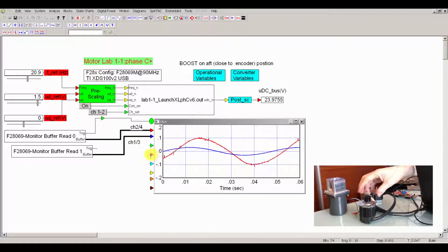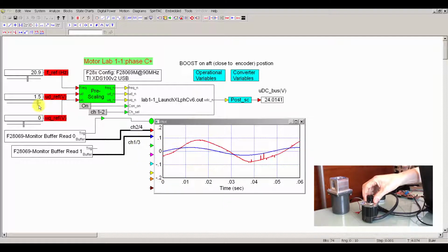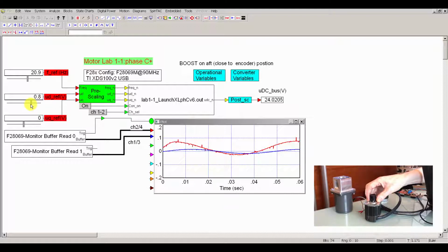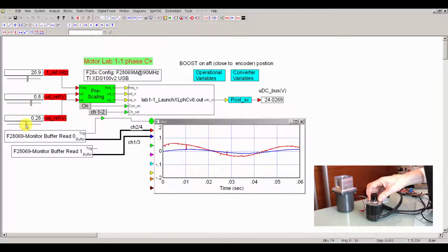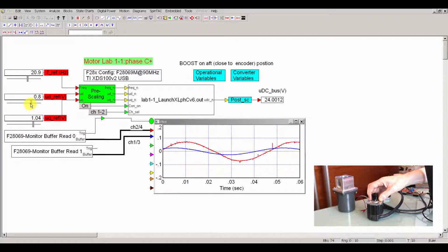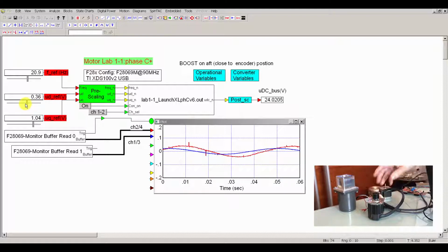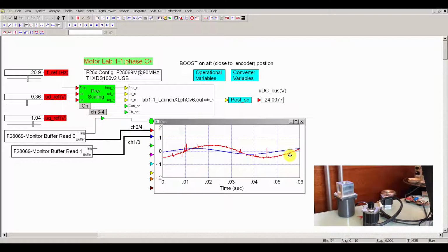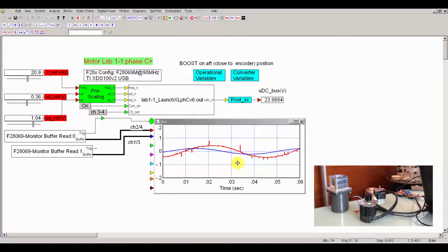This is the first step. Now, we've set UD to a certain value. If I set UD down to 0, for example, the voltage becomes less, it won't work. I can increase UQ, and now that I've set up UQ, I can set UD to 0. Exactly the same thing as we did in the simulation. Again, you can confirm operation, and you can select different waveforms and look at any point, at any time in your converter.